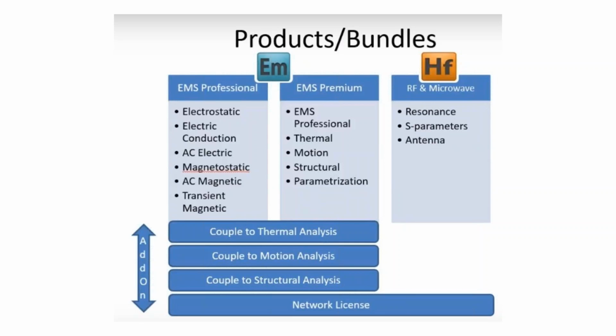Coupling to SolidWorks motion is mostly useful for computing the induced voltage for different speeds of the voice coil, and definitely the higher the speed of a voice coil, the higher the frequency of motion, the higher the induced voltage would be, and that would also have big implications on the amplifier design, or the amplifier that you need to use in your device.